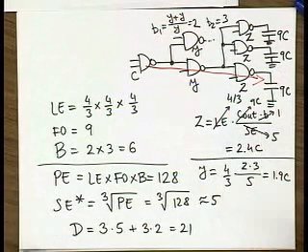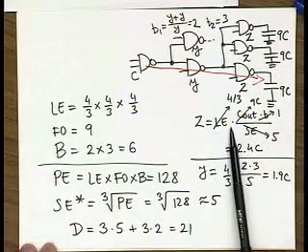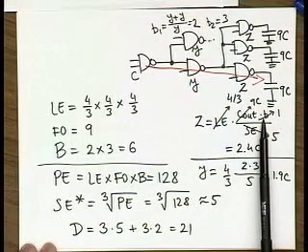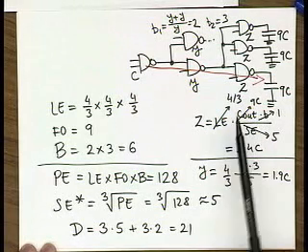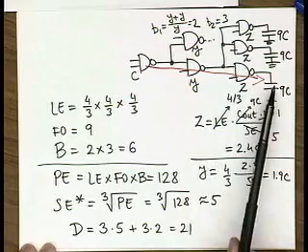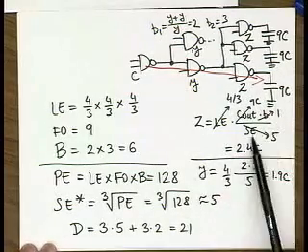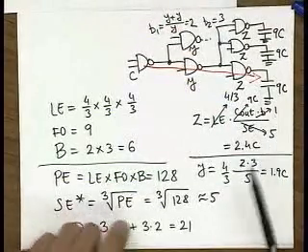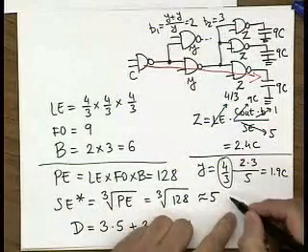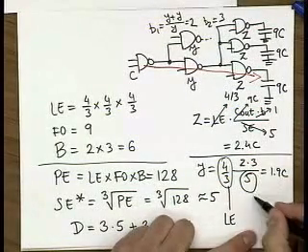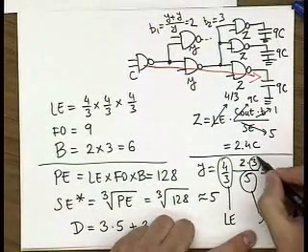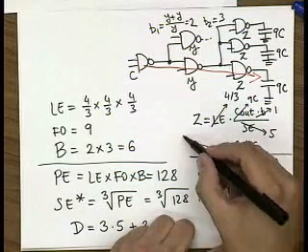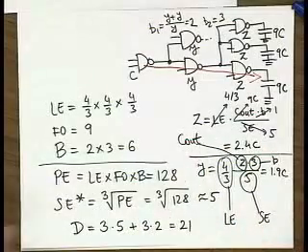So basically we use the same formula that we used before. You have logical effort, output capacitance divided by the stage effort and times branching. So when you calculate Z, the output capacitance is 9, the stage effort is 5, that's what you calculated. Branching is equal to 1 because this doesn't branch anywhere. For the Y, this is your logical effort, this is your stage effort, this is your branching, and this is your C out.